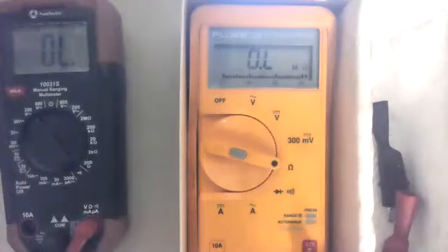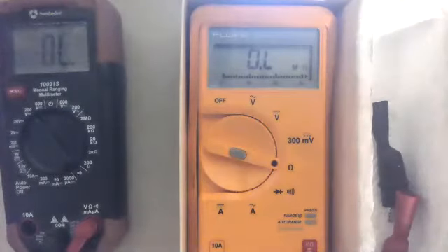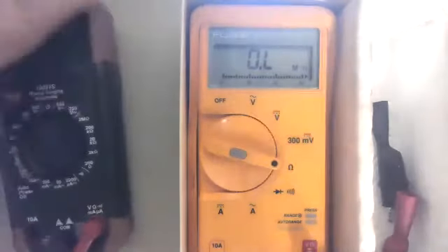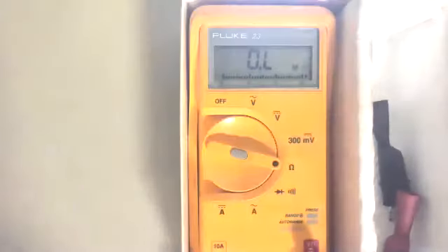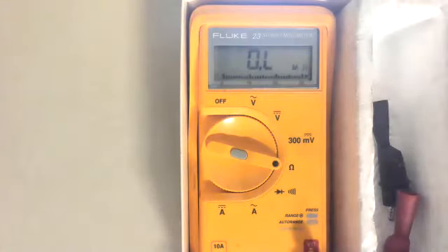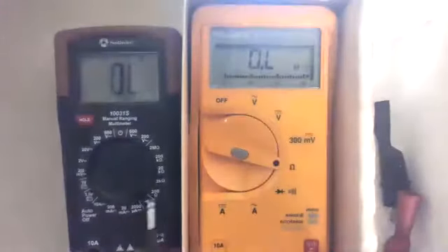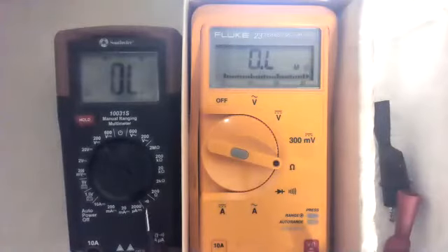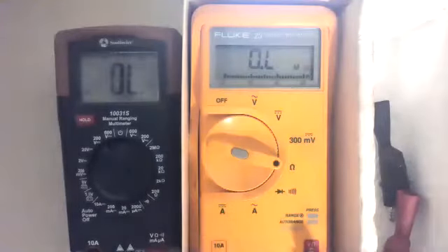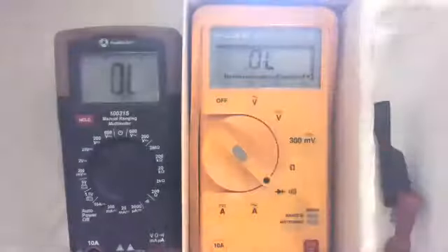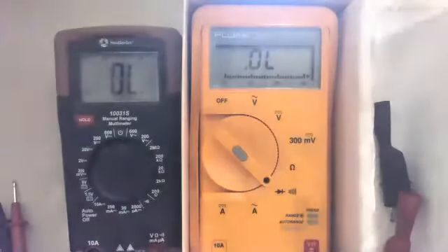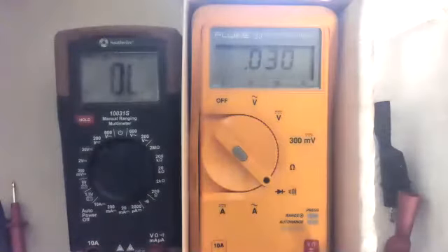I don't know if you can hear this. I don't know where the speaker is, but I'll put it up here, kind of where I talk. You can probably hear that. So anyway, that's all that is. When you're measuring resistance, that little line symbol here will tell you audibly, with noise, that you have a connection.